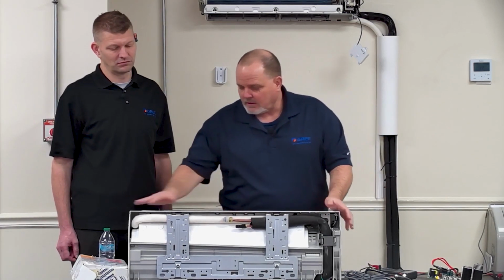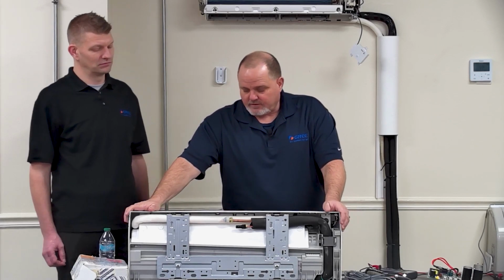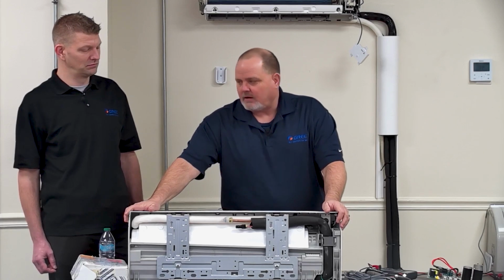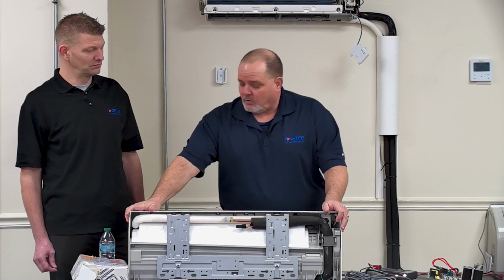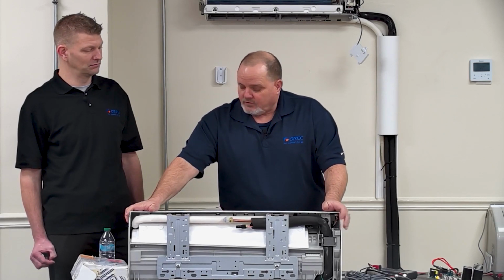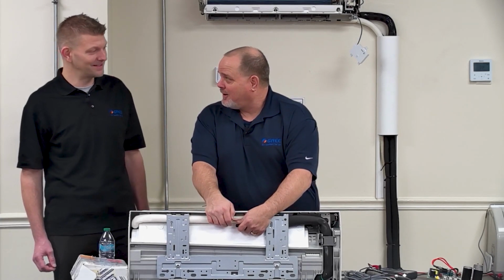And then, I guess the other thing I could talk about is let's say for whatever reason, and we don't have a lot of leak problems with our units and stuff, but let's say this wall mount got a leak in it, and I need to replace it, and it's under warranty, and we end up replacing the whole head instead of just the coil. Well, at that point, it's going to be a lot easier just to undo 2 flares. Way easier.